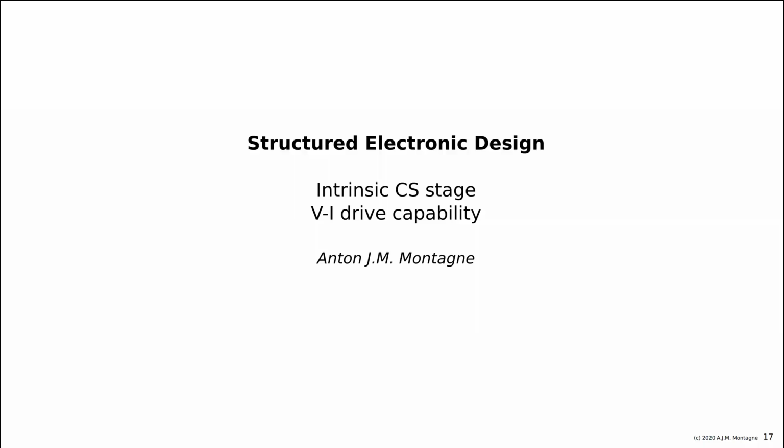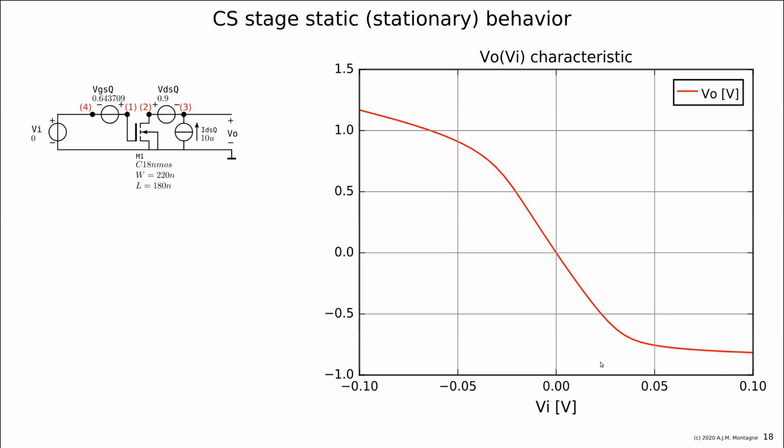the voltage and current drive capability. And there should not be a big miracle because we know exactly what we have defined. We have designed 0.9 volt negative excursion and 10 microamps positive excursion. So let's see if we make a plot what we get.